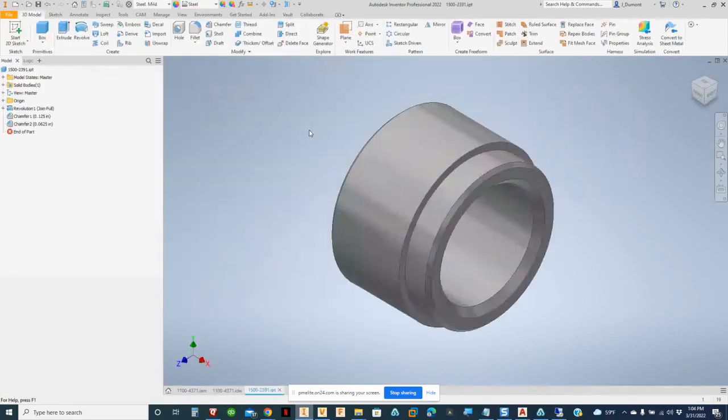when you go to the iProperties. A lot of times we want to fill in that metadata so we have information, we can search on it, and a lot of times that information is brought into the title block. So you want to go back and fill out the iProperties, but in this particular file, I have the Vault ribbon just displayed over here, and the file is not checked out.